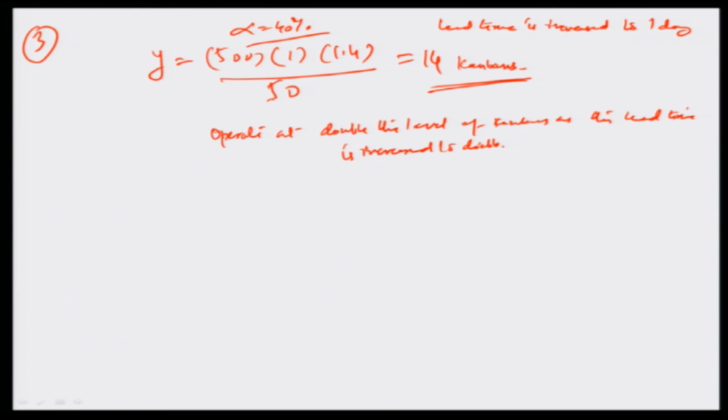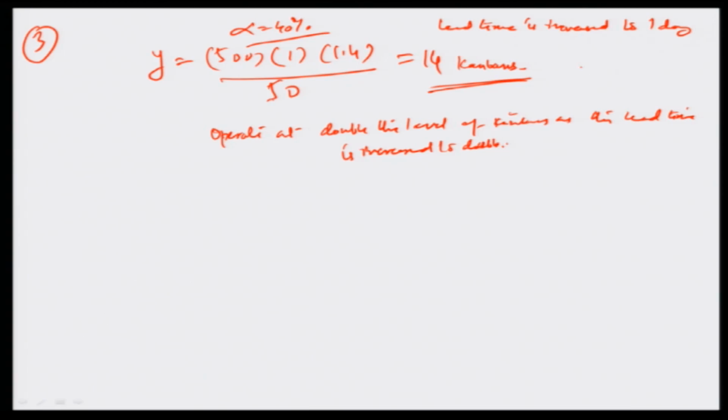So, whatever model you are proposing actually works out very well here, that now if the lead time is increased from 0.5 days or half a day to a single day because of whatever issues, the Kanbans should also get doubled, because then you are accommodating a greater period and you have to buy more stock and keep more stock in question, okay. So, the stocking area gets increased by 7 bins, about close to 350 components more, and that is how the inventory level goes up.